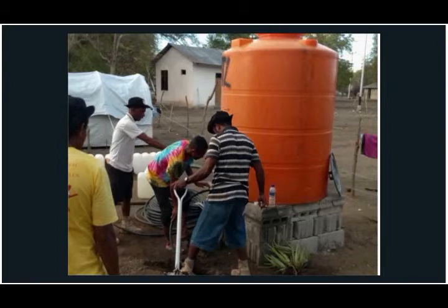The second type of material that is used is called a data logger, which is an automatic measurement device, and it usually is lowered into a borehole below the water level, and it measures the pressure of the water. Pressure is related to the height of the water level, so it can calculate the height above the data logger. So at a particular time, you can pull that data logger out, connect it to your computer and download the data from the data logger.